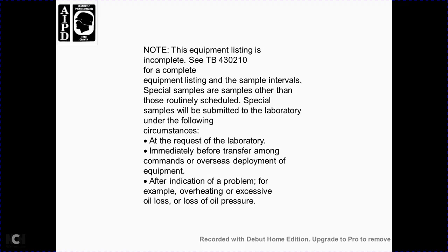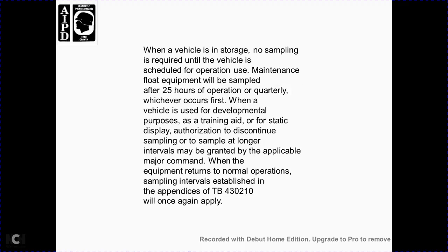Special samples are samples other than routinely scheduled intervals. A special sample is submitted to the laboratory under the following circumstances: at the request of the laboratory, immediately before transferring among commands or deployment of the equipment, and on indication of a problem, for example, overheating, excessive oil loss, and loss of oil pressure.